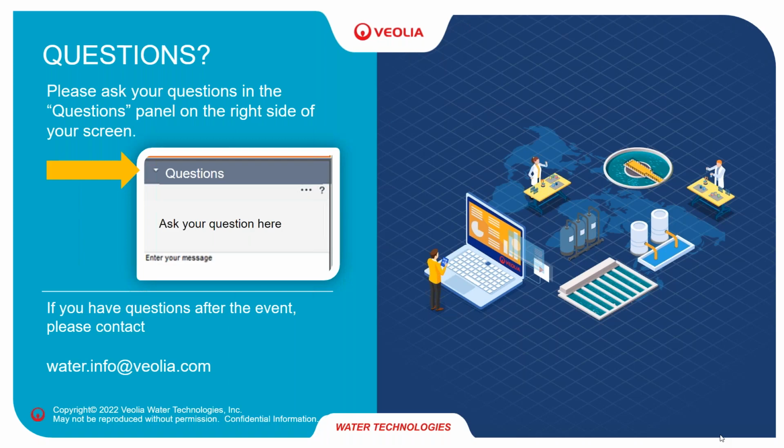So there is some stress for sure applied on the nitrifiers during backwash. The filters have probably less aeration, and they are physically shaken. You could measure some N2O spikes for just a few minutes, and there's probably something to investigate there. And I know there were some pilots done to try to mitigate N2O emissions, especially concentrating on these periods right after backwash. But as a general answer, similar to activated sludge.